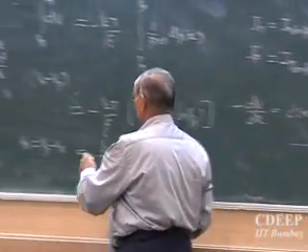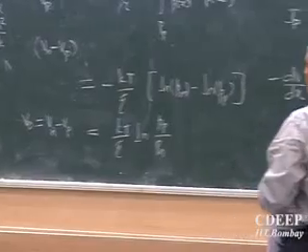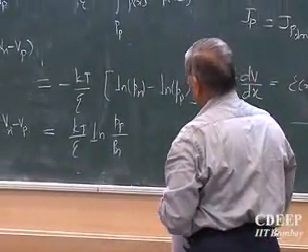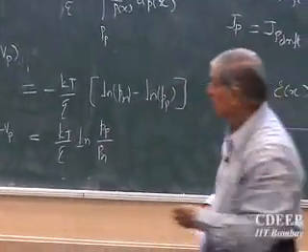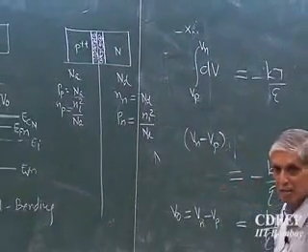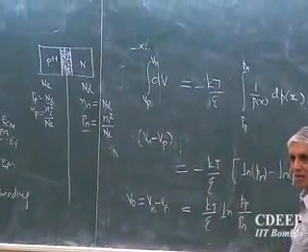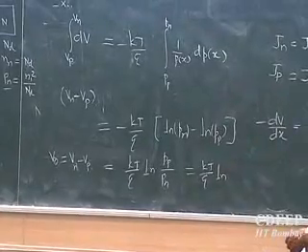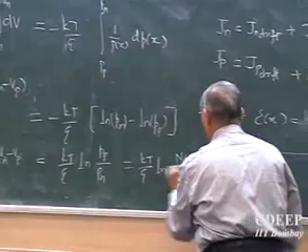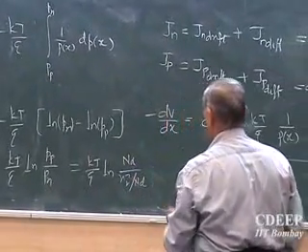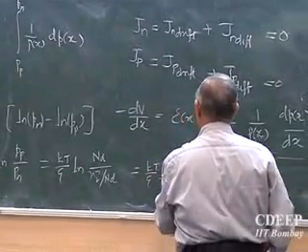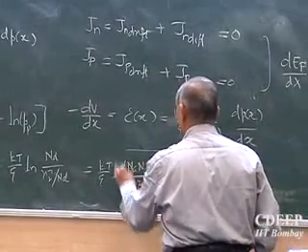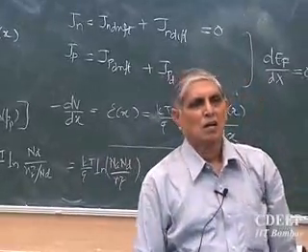You can define it the other way also. That's not a very important issue. The minus one will come from this. So how much is p_p that I wrote there? p_p is Na. p_n is ni square by Nd. So how can I write this? What should be the expression? Both Na and Nd I have now taken. p_p is Na divided by ni square by Nd, which is equal to kT by Q ln Na Nd by ni square. Is that okay? So V0 is essentially kT by Q ln Na Nd by ni square.